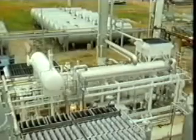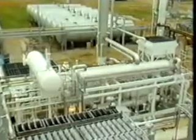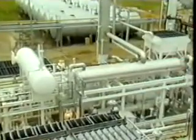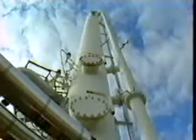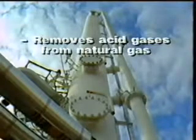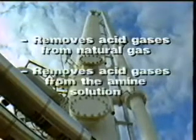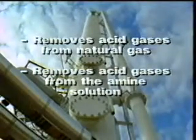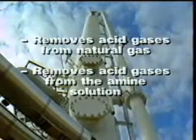To keep production costs down and improve the overall efficiency of the system, the amine solution must be recycled. So there are really 2 purposes of an amine sweetening unit. Primarily, it's used to remove acid gases from natural gas before it enters a pipeline. The unit's other purpose is to remove acid gases from the amine solution so that the amine can be used over and over again in the sweetening process.